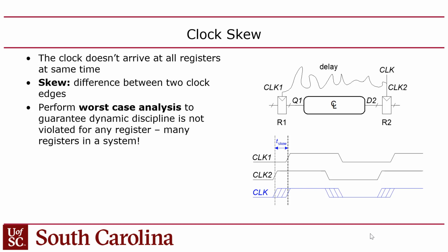When the clock toggles, there's so much metal that not every flip-flop is going to see the clock edge at the same time. The clock comes in almost like a wave. Flip-flops that are closer to the clock source will see the edge before ones that are farther away. Does that make sense? Every chip has what's called clock skew.